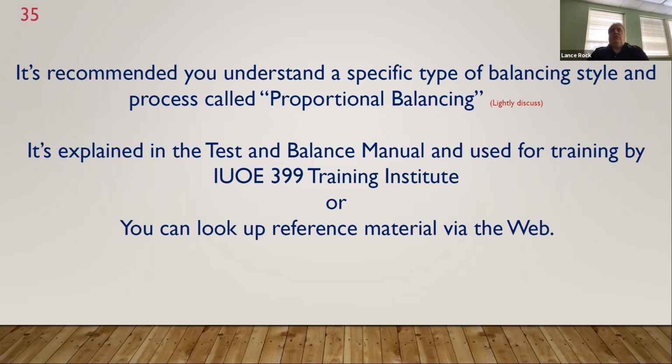So if that lowest terminal device is at 50%, and there's, we'll say, 10 terminal devices, and the next lowest one percentage-wise is at 60%, you won't balance that next terminal at 60% into the 50. You'll assume that 50% will come up a little bit. You may drop that and shoot for a number of 61 to 62% of design on that second device. And then when you go to the third, you might shoot for 65%. And then when you go to the fourth, it could be something well over design, and you might be shooting for a 70%. But when you're done, you don't have to go back and rebalance damper into damper, diffuser into diffuser, terminal into terminal. When you're done, you simply read it out and you record your flows. It's really a one-pass balance that works really well.